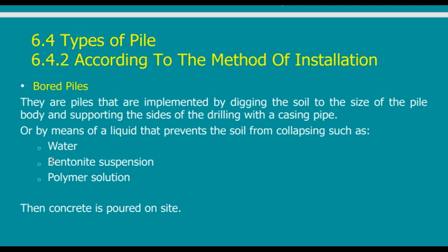It is suspended in the water. It keeps the water all the time moving, so it prevents the sides from collapsing and closing the hole, or at least delays this. So bentonite is okay. Sometimes we call it in Arabic بتليس الحفرة. It covers the sides of the hole.